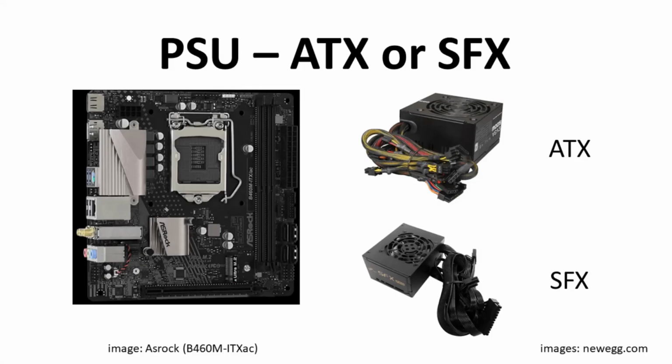I've put off discussing the power supply as long as possible. It's messy, so let's look at a few scenarios. The first is easy. Larger ITX cases have space for a full ATX power supply. The typical ITX motherboard has a standard 24-pin connector, barely visible in this image, as well as a 4 or 8-pin CPU power. And everything works like any other motherboard.